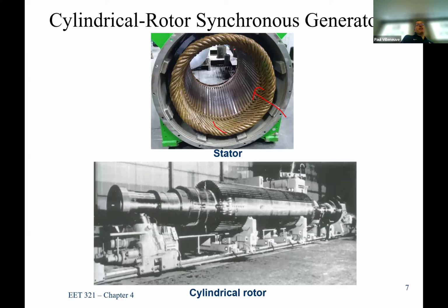You've got to put bearings at the end. So you actually have the shaft sitting on the ground. But what you do is you slide this unit in very carefully because you don't want to damage the windings. And sometimes the air gap is 20 millimeters, very, very tight gaps. So you've got to slide it in very carefully. And then at the end, you have to mount it to a support for the actual rotating part. So alignment is really crucial.